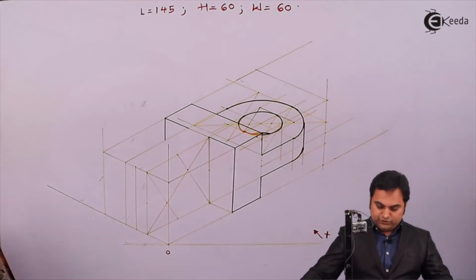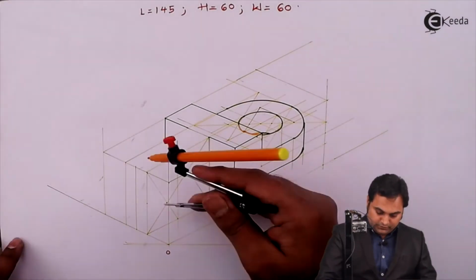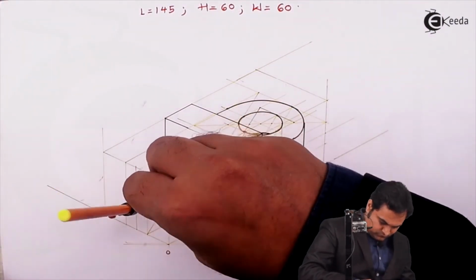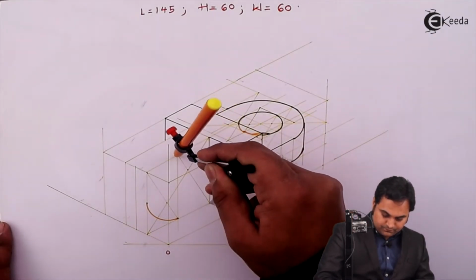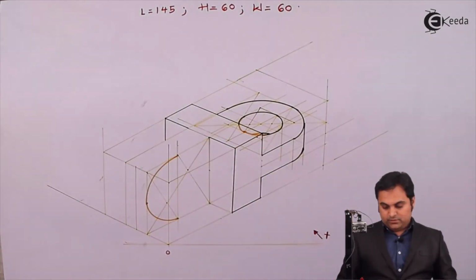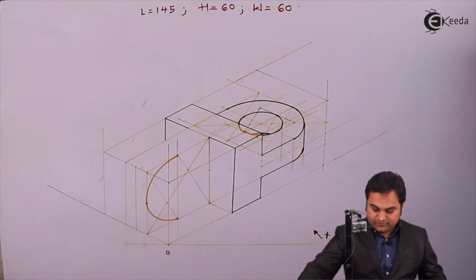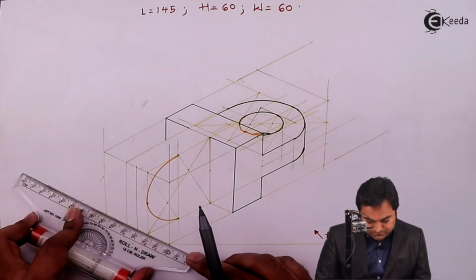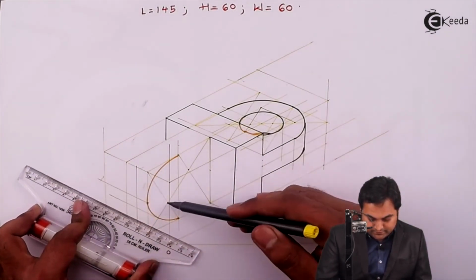Then I want the semicircle portion only up to this region, and for that, here I'll take this center, this much radius up to the midpoint. Then keeping this center, this much radius, drawing an arc. Now this is the semicircle. The same semicircle will be drawn 20 mm behind because that is the width of the semicircular part. For that, the first point which I'll project back is the arc cutting the longer diagonal, projected back. Then this midpoint will be projected back, and this center which I had used.